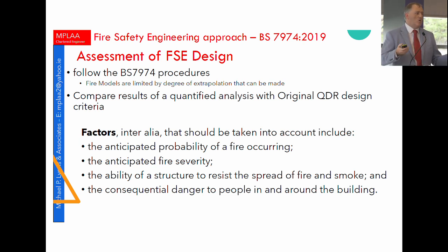So if you've no sprinkler system to control the growth of a fire, it's going to get very, very hot in every room of origin enclosure wherever a fire occurs. So no one's alive at 600 degrees centigrade. So therefore, when the flashover occurs, and flashover can occur in a very short period of time, everybody needs to be out of that enclosure. So in a performance-based design, you've got to include the degree of severity that will occur in your particular design.